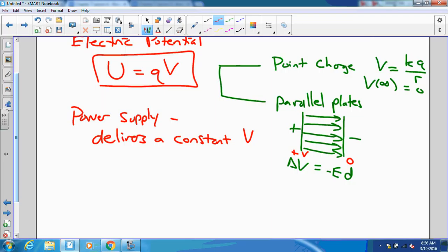12.37. See how my voltage drops? And as I get closer to this part, well, let's go all the way to here. So notice that all along this piece of conductive ink, my voltage is basically 0. And all along here, 13.5, 13.6.